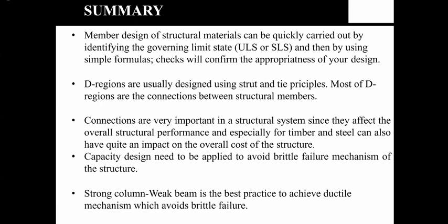Member design needs to be done for different limit states, and you need to make sure it satisfies strength criteria and also deflection criteria: capacity is more than demand, and deflections are within allowable limits. And if you have connection regions, most of the time Euler-Bernoulli theory is not going to work. You might have to use Strut-and-Tie type principles, which I haven't talked about, but you need to make sure the connection behaves as it should, right? Connection is very important in your structural system, as it transfers loads from one element to another, and its stiffness and strength can really alter your overall system behavior.